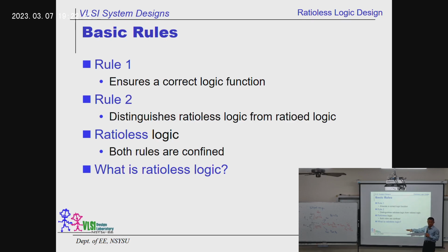not. So those circuits that I demonstrated yesterday and earlier in this lecture are ratio-less. But if you find there is a point, a summing point or any point, where the output is coupled to the VDD and the ground simultaneously, then you are guaranteed to have a ratio design.